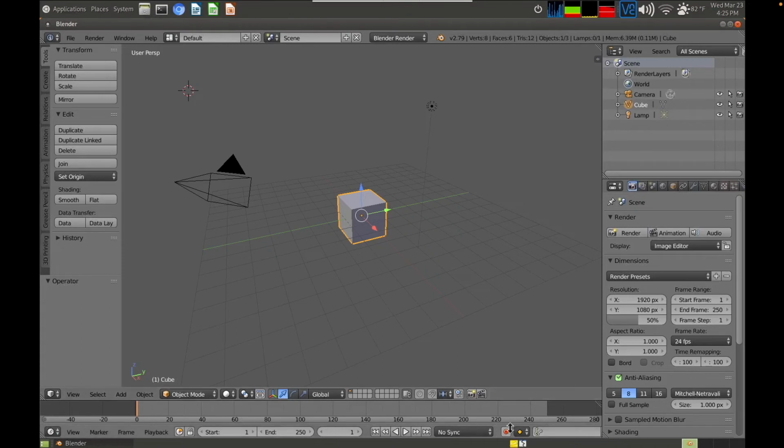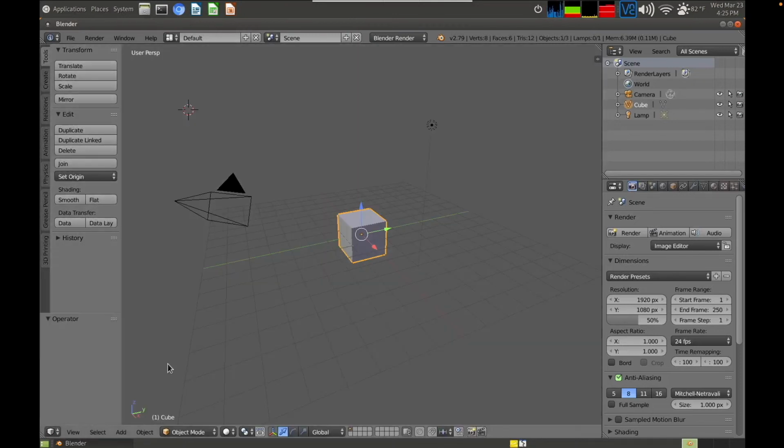So what I'm going to do is actually combine our viewport area with this timeline area to give us a little bit more space. So down here at the bottom of the viewport editor, I am going to drag down to combine. And now we just have the viewport editor, the outline editor, and the properties editor. And of course, the information editor at the top, which just gives us information about the things that are going on in our program.